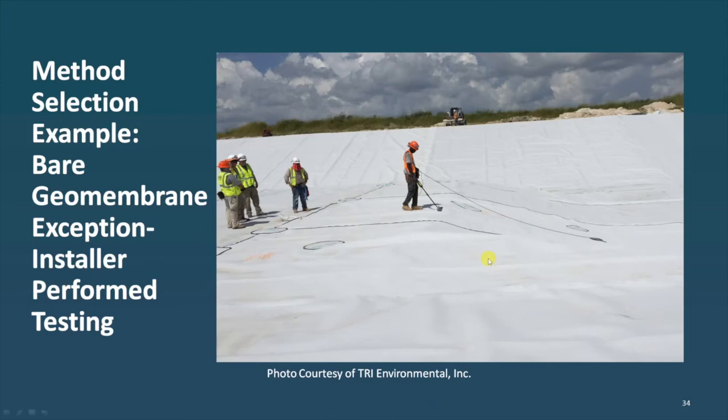This particular photo is from a spark testing project. So this is a conductive back geomembrane. And I was hired as kind of a method auditor. So I went to site and I watched them do this spark testing, and basically told the owner whether or not they were doing it right to help them make sure that the testing was done appropriately. So whether or not you have an audit of the test, I think it's a very practical way to go to have the installer check all of their work.